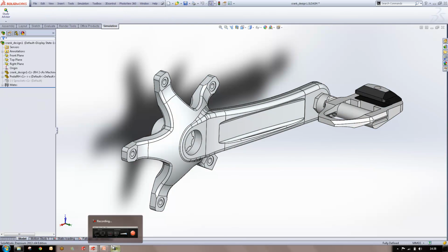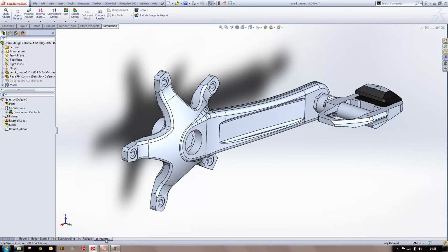So that's a very nice feature that SolidWorks have added, giving this the opportunity to switch in and out of our study with relative ease, which is something that you won't get in a lot of other packages where perhaps you might have to export your geometry into the full design environment, and then if you want to make a change, you make the change to your geometry in SolidWorks and export it again and reset up the study. This is very simple because all of the selections are based on the internal IDs of the faces and the geometry that you've got on your screen, so when you make a slight change, SolidWorks remembers everything else and will keep it all set up for you.